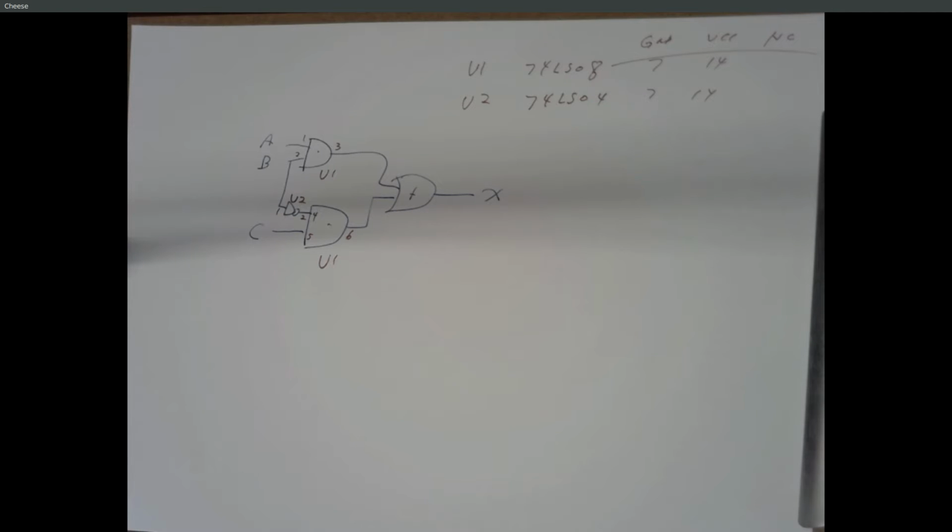Yeah, make sure you indicate what ones and zeros mean when you're writing your system diagram. Here's inputs A, B, and C. That's a good place to say 0 means there's a car present, 1 means there's no car present, or whatever convention you're using. Because it's up to you, right? What kind of sensor you're going to use. You might have a sensor that generates a 0 when a car shows up. You might have a sensor that generates a 1 when a car shows up. Perfectly valid, but just let the reader know what type of sensor you're using, right? What's the 1, what's the 0 mean?